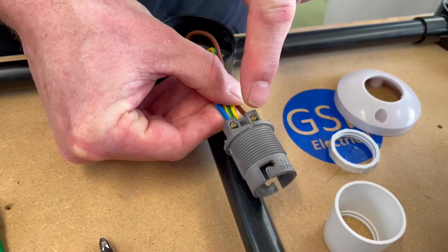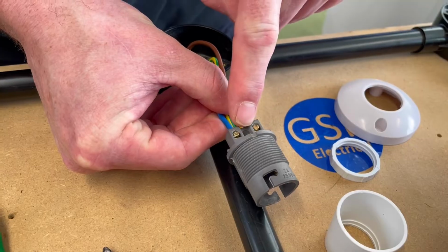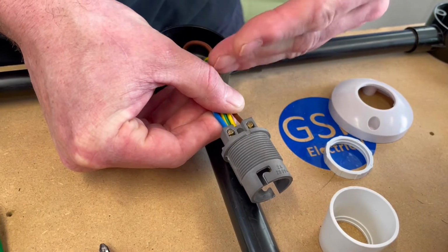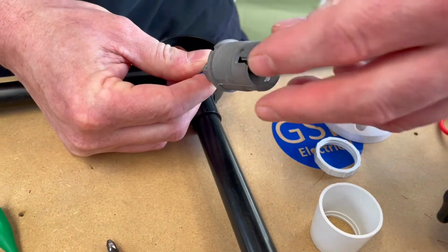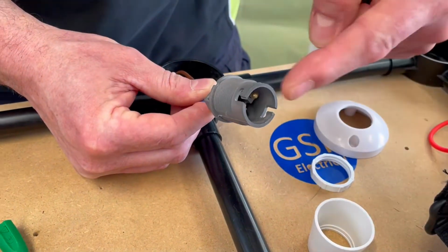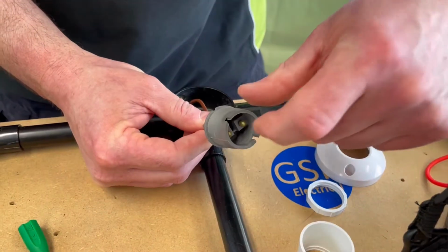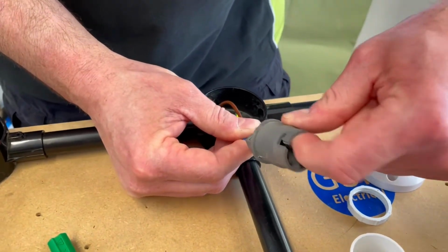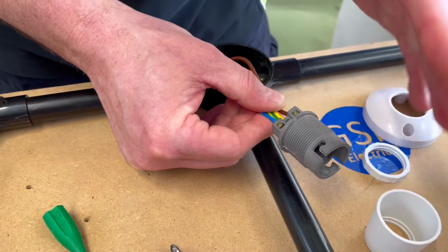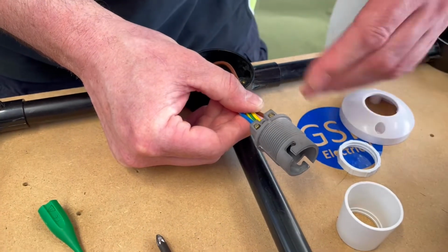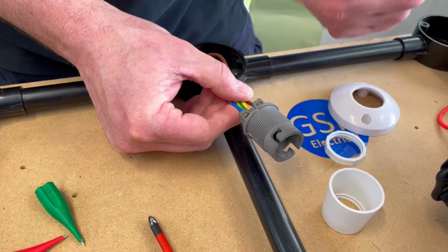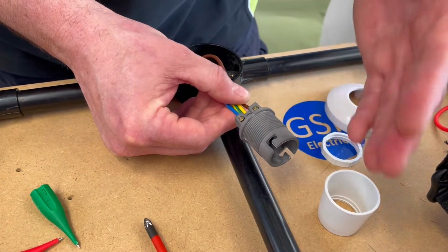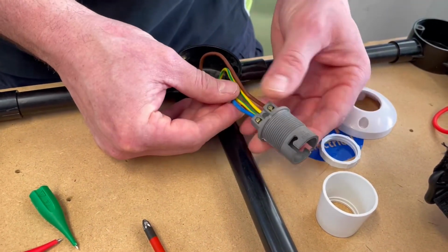We're going to test between the switching line conductor and the CPC here, and then we're going to operate the switch at the same time to prove it comes on and off. There are adapters that can go into the end here, so you could get actually onto the final pin, or you could try and push onto this pin. Remember, this is a test that we're carrying out very early on, first 10 weeks, and we're just looking to go through the fundamentals of a continuity of CPC and polarity test, and we make it more advanced as we move through our levels towards our endpoint assessment.